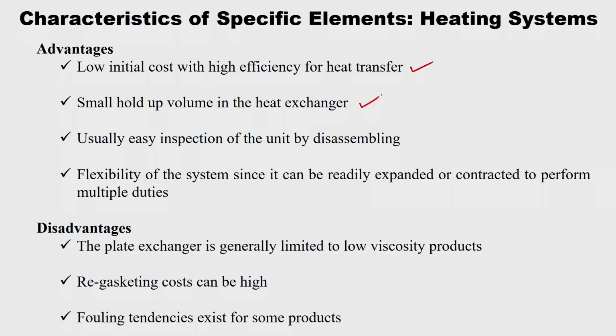And advantages wise, there is low initial cost with high efficiency because of regeneration, a small hold up volume in the heat exchanger, and usually easy inspection of the unit by disassembling. Actually what happens here is I can remove the plates and I can reassemble them. For example, we have done one problem, right? How many plates are required in the heating section or regeneration section or cooling section?